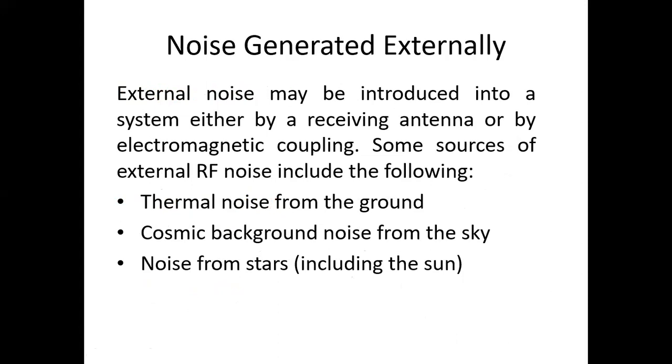How do you get this thermal noise? Those types of noise you may get from the circuit you have. But there can also be noise from the external environment, like from the ground, from the sky, or even from the stars. Wow, but that must be very low. So it depends on how sensitive your equipment, your circuit, is. For very highly sensitive equipment, this type of noise you may have to take into account. These noise levels are very, very, very low, definitely. But there is very sensitive circuitry in space shuttles or space stations. So you may have to take this noise from stars into account for those types of circuits.